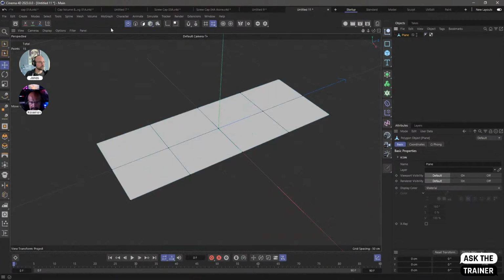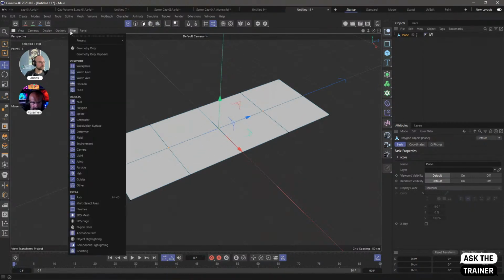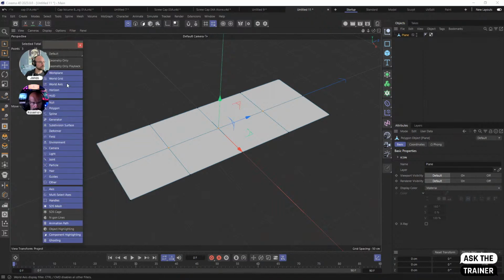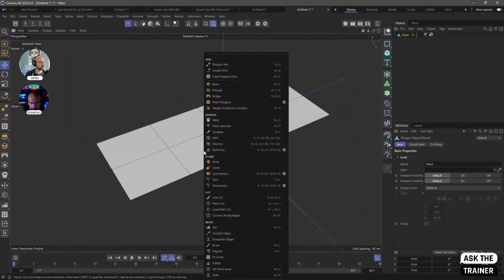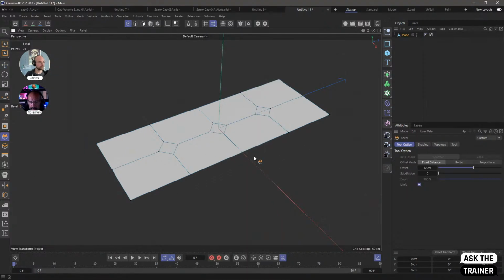The way I like to make holes on flat planes, and I'm going to remove workspace, work plane, and horizon, just that. Select these 3 points, right click and bevel, right? Good, so we have these squares. Now another rule, so to speak, about subdivision surface is that the lowest number of points that will give you something close to a perfect circle are 8. And I have a little example I'm going to show you in a second.